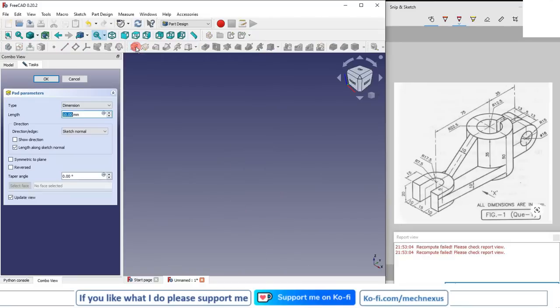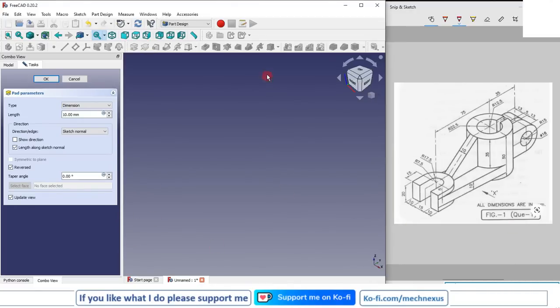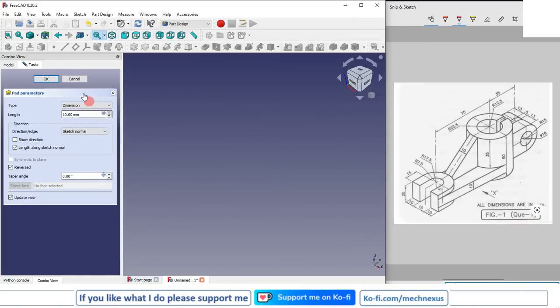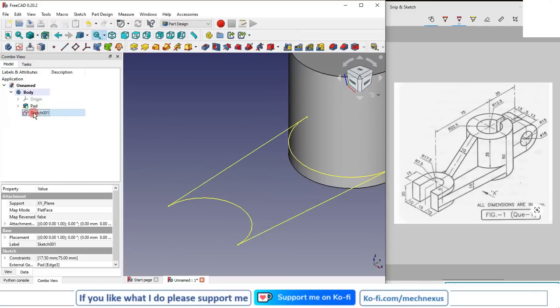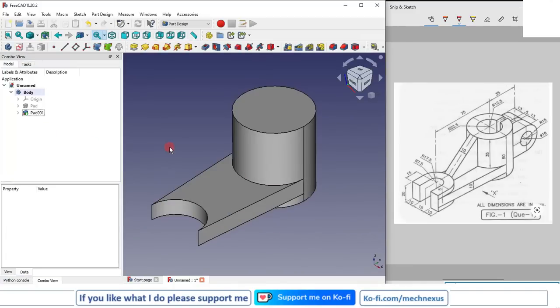So I will go on the pad and I will click on here reverse direction. So here is a recompute failed, so I will on my report, so it is a recompute problem, I will cancel it. Let's select the sketch, again click on the pad. Okay, so it was a solver issue. Now I will say okay.